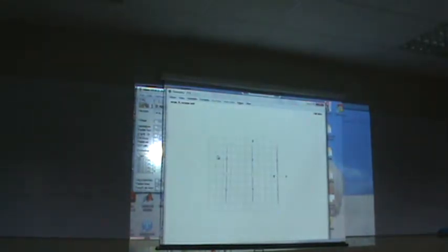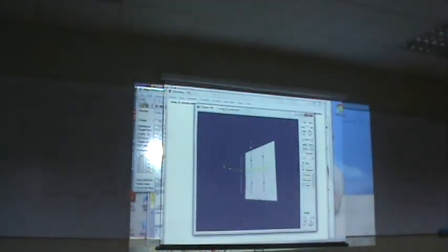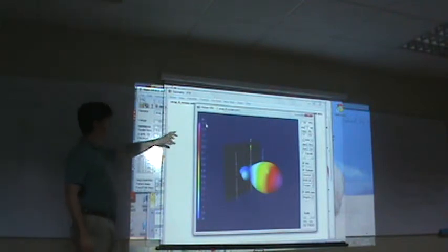Okay. This is an antenna with 6 elements and a screen behind. And if you look at how this antenna radiates, yeah, the radiation is really concentrated in one direction, in the frontal direction. The gain is very high, 13 dB. 13 dB means 20 times.